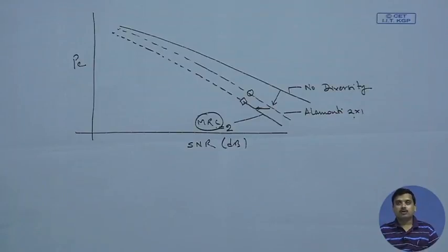So what we have seen till now are spatial diversity modes. You could have channel state information at the transmitter, as well as without channel state information at the transmitter you could also gain diversity. But with the special scheme that we have considered, the Alamuti scheme, which is a very simple scheme, you can get the same order of diversity gain, but the array gain is not available, which is there in the case of channel state information being available at the transmitter or in the case of receive MRC.